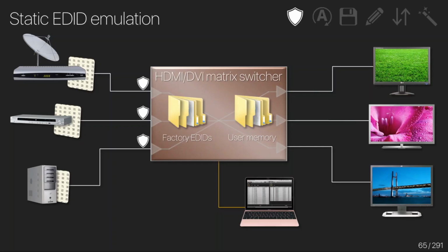So in this example, if we remove a display and we connect a new display, the image is displayed on the new display, and there's no issues because the EDID of that display is not actually being used by any of the source devices.